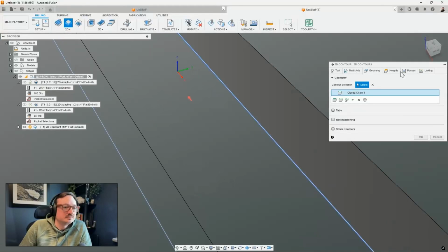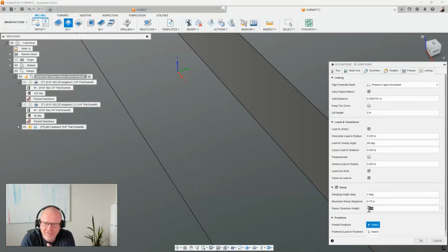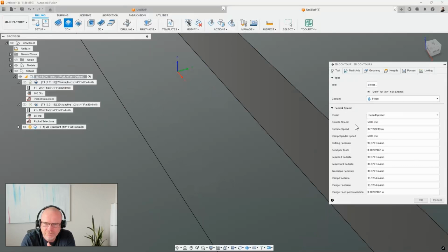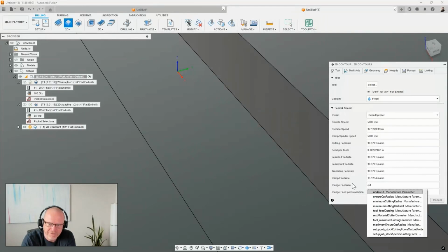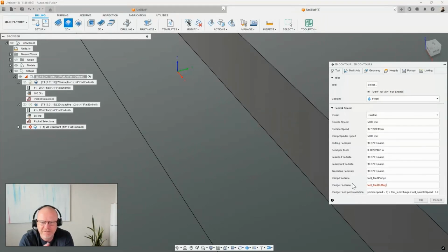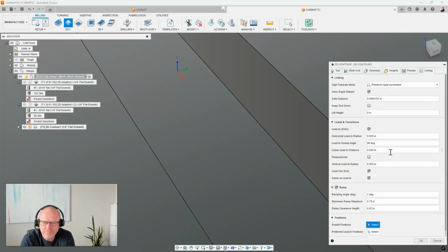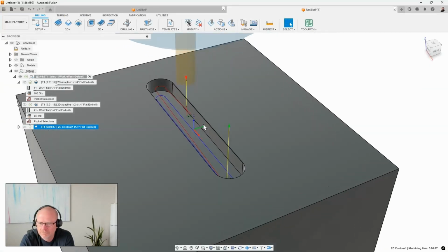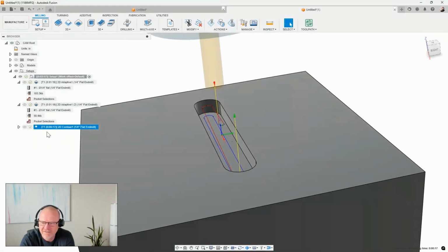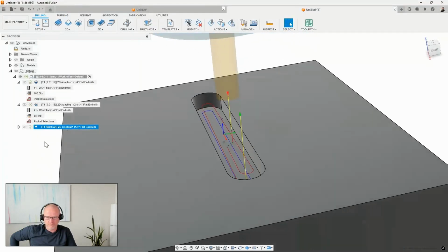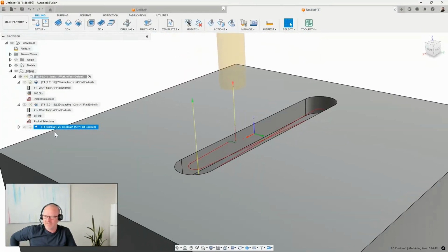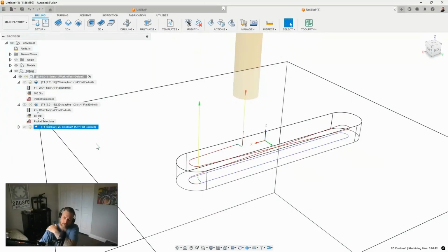Yeah. If you were to do a ramp 2D contour with the ramp, and compare the cycle time with the same speeds and feeds. You could probably make that ramp angle like 30 degrees. I find it funny that the cycle time... Oh, it's the same. I was looking at the wrong thing. Yeah, see, 17 seconds compared to a minute and 19, so a whole minute faster. So Phil highlighted that by bringing that up. Way more efficient on a geometry like that. And if you're doing soft material, that's perfect.